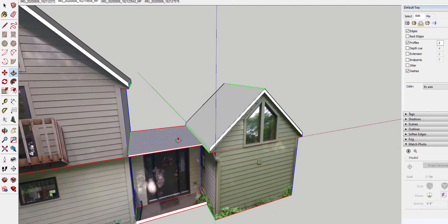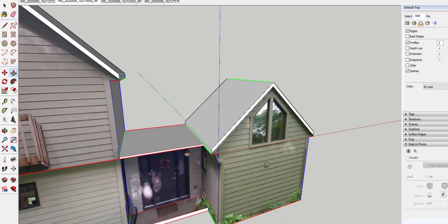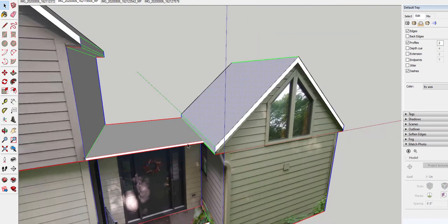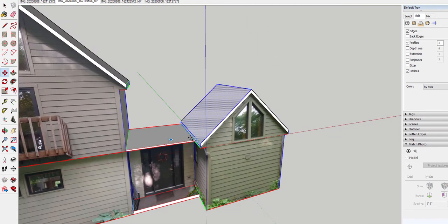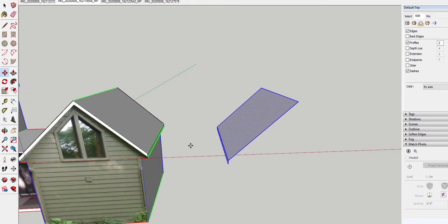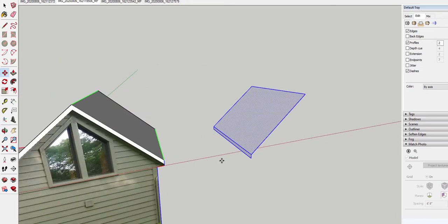Okay, well, to get this piece here, I'm going to copy this slope and put it in position. So I'm going to select this surface, hold the Control key, select this surface, use the Move tool, tap somewhere and go across, and that's the shape of this slope. Use the Rotate tool, and you can rotate in the blue, the red, or the green, and that changes depending on the axes that I'm pressing on my up, down, left, right keys.